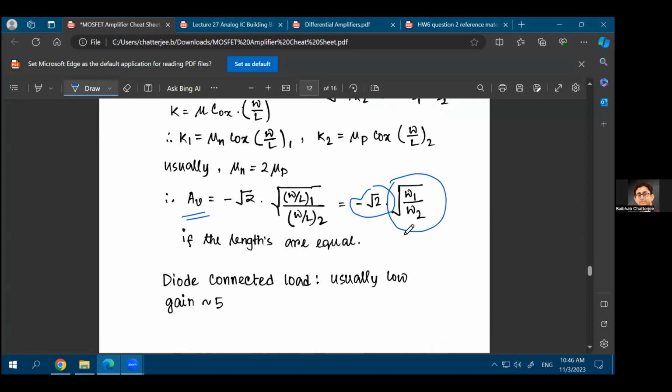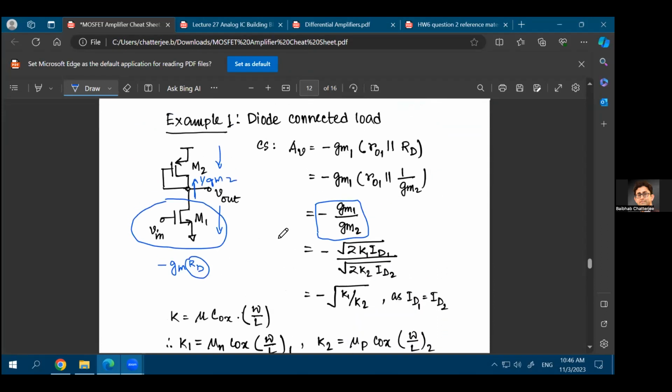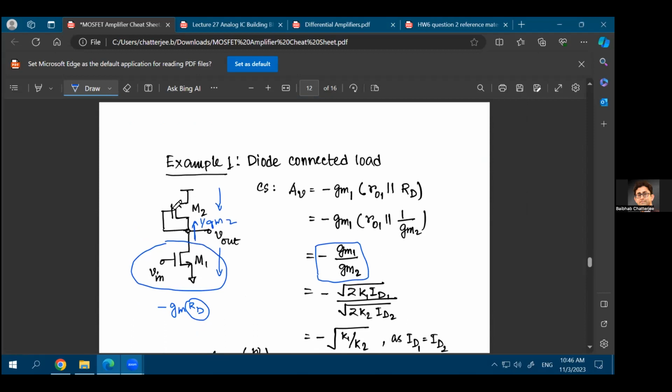And that is because it makes it much harder to connect, let's say, different transistors. So, for example, this is one transistor, this is the other transistor. Let's just assume this transistor is 100 times bigger than the other. Then making all these connections to the gate and the sources and the drains, connecting this drain and the other drain together becomes much more troublesome, if one transistor is much larger in length and width than the other.